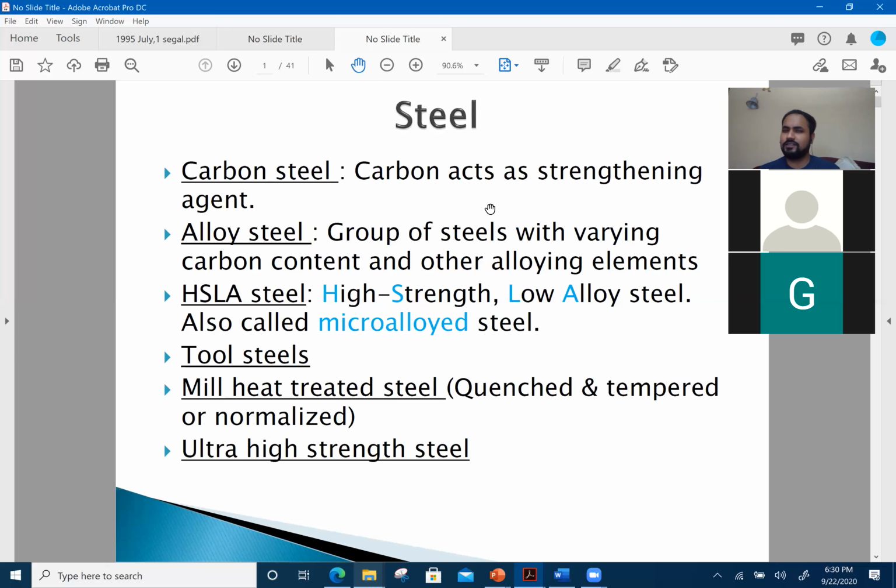That's a good point, actually. I never thought from that point of view, because it's on the further right side, so it forms after a long time. Because I would think that at lower temperatures than the A1, A3 line, you would be forming pearlite, regardless of how long you kept it there, even if you didn't go all the way down to room temperature. Pearlite is just a term given. It's basically a ferrite and cementite mix. So you do form pearlite even if you're ahead there.